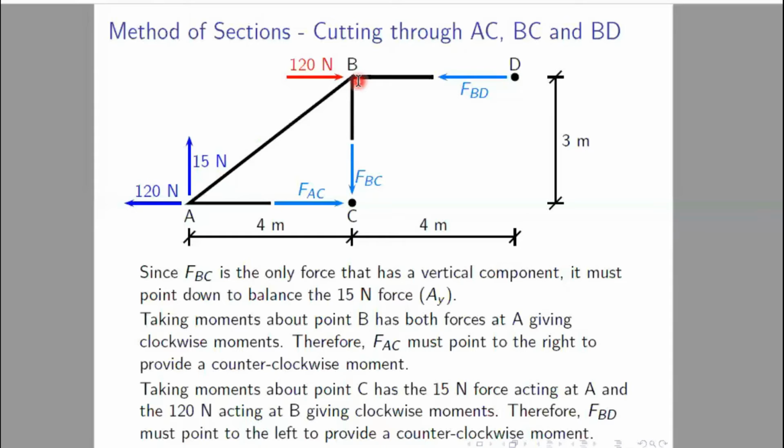So there will be some anti-clockwise forces acting within the structure in order to maintain equilibrium, that is, sum of moments at point B equals zero. We have the unknown reactive force in this member, that is FAC. In order to maintain equilibrium, FAC must be in the anti-clockwise direction if we take moment about point B. That's why we have shown FAC in the anti-clockwise fashion. So it comes out to be a tensile force as far as the sign convention is concerned.